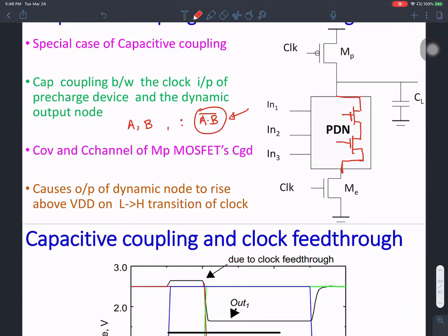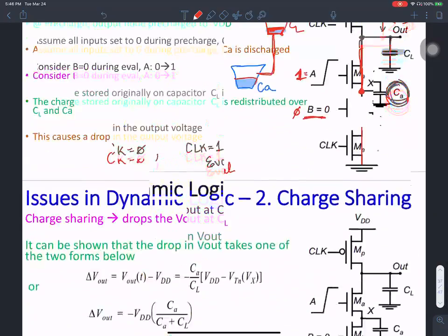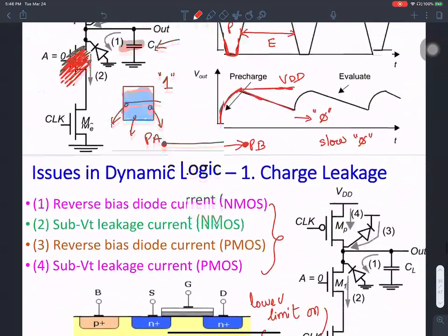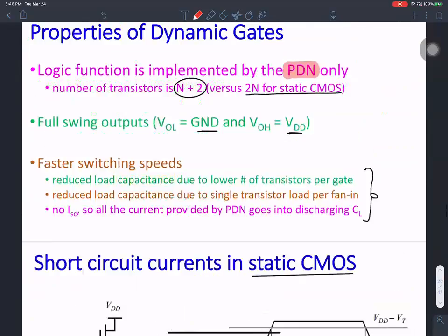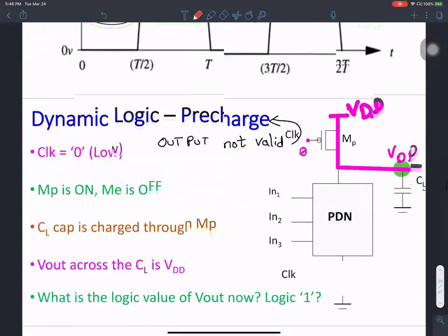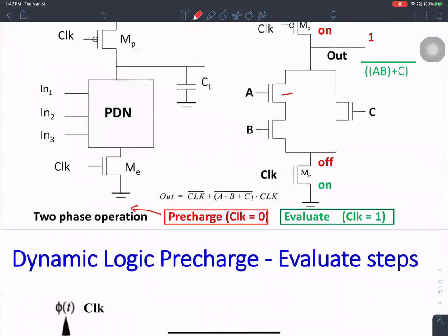As a matter of fact, let me go back a few slides. I'll show you the expression for the logic gate. Right here. I have one NMOS in series with another NMOS in parallel with an NMOS. So I have A times B plus C. That corresponds to the series and parallel combination, and the whole complement.